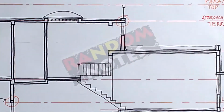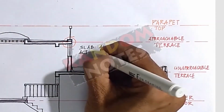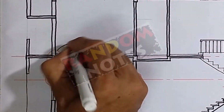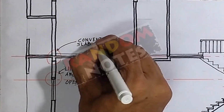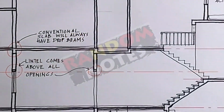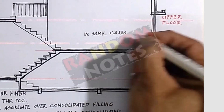In some situations, slab can act as a lintel for an opening. Conventionally, all slabs will have a drop beam around the slab as per architectural and structural design. In some cases, depending on the need, we may also have an inverted beam.